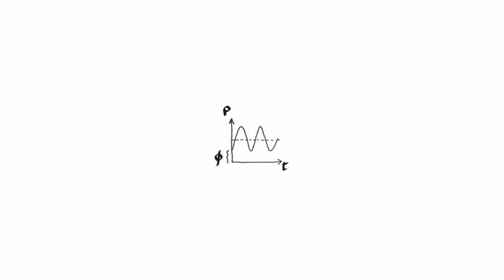But their mistake is almost logical. For sine waves, switching the polarity is equivalent to changing the phase by 180 degrees, since two sine waves out of phase by 180 degrees will cancel out. Note that two signals can be in phase but of opposite polarity and of course perfectly cancel each other out. That is in fact the only way to cancel two signals.